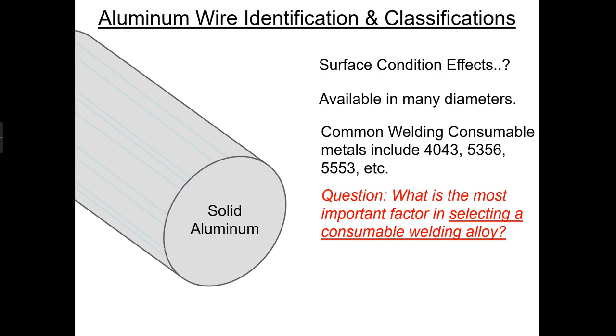There are a few other options. In fact, now there's dozens of options for welding 6061 or any type of structural aluminum. But one important point I want to mention here is that this rod, this wire, is not the same as the material you're welding, and that's a very specific metallurgical mix. I'll take this moment to stomp the idea that it's a metallurgical solution. You have to remember that this filler material needs some of that base metal mixed in with it to help with its strength characteristics.